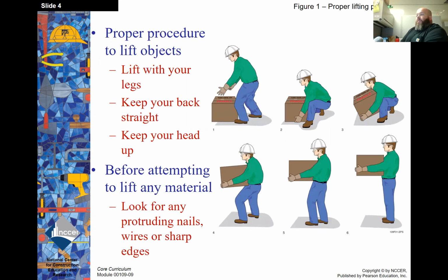When we look at lifting, there is a proper lifting procedure. You want to lift with your legs, keep your back straight, and keep your head up. Before attempting to lift any material, look for any protruding nails, wires, or sharp edges.